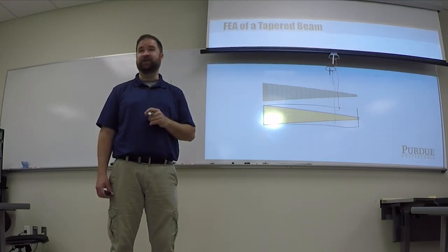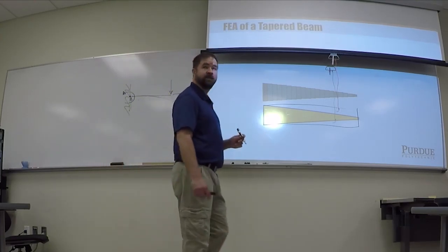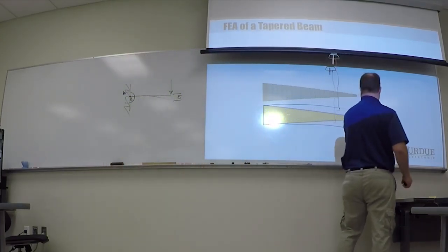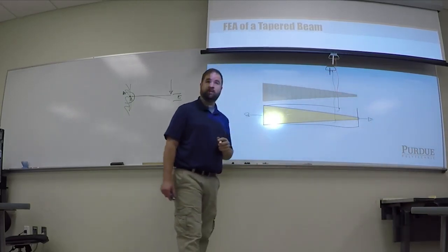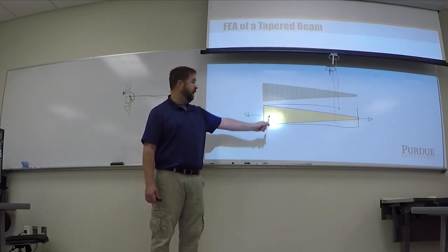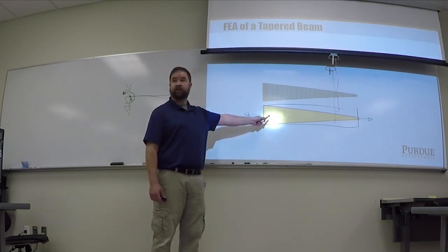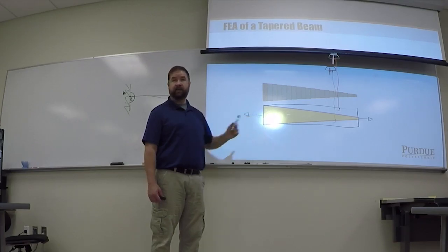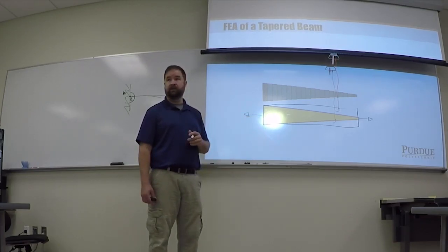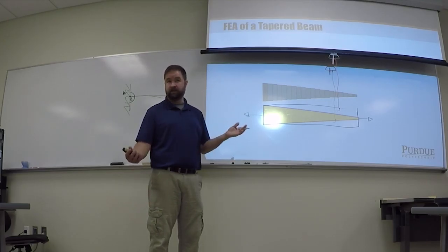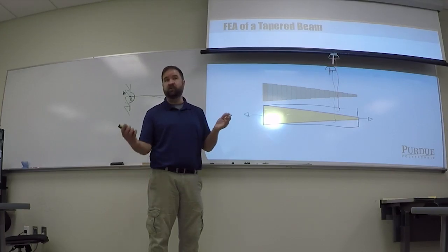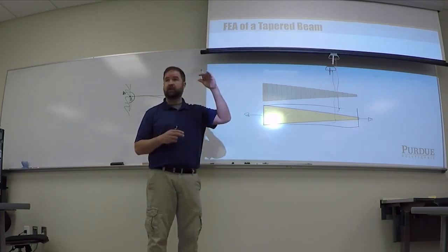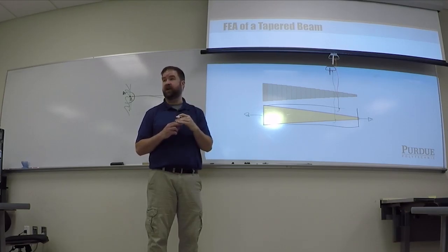I heard both bigger and smaller. Well, one, you're not going to move as much. Yeah, so I'm pulling on it this way, and I'm modeling it with this rectangle. If I do that, I am overestimating the amount of material here, right? And since I'm overestimating the amount of material, my deflection is going to be smaller than it should be, right? But I could use that to establish a bound, kind of like a best case scenario. It would actually be a lower bound, right?